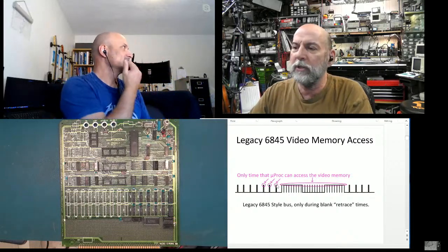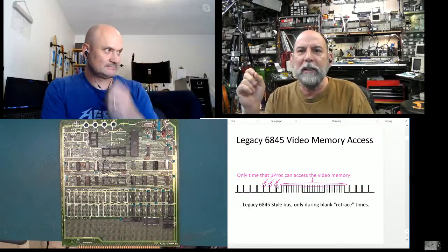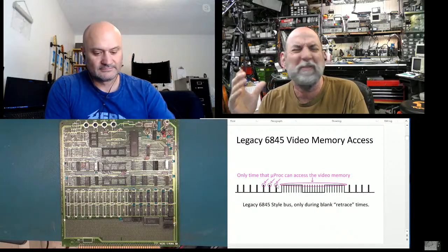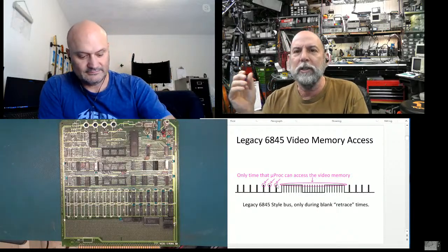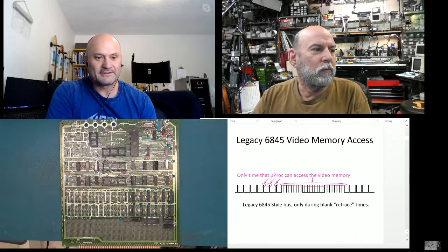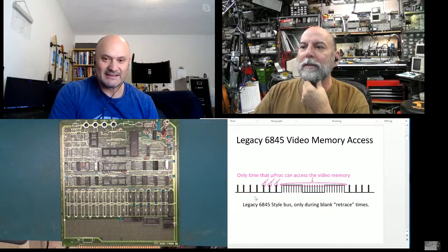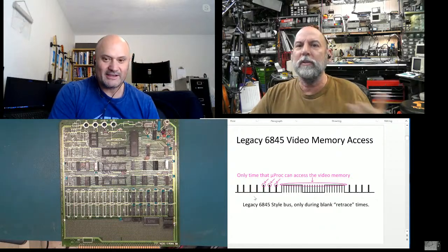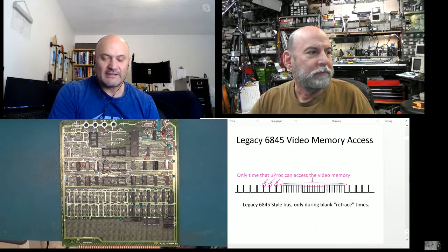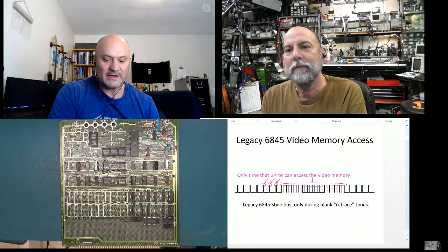I don't have something that shows the full frame, but it's real minimal. Out of 63 microseconds, you might get 6 or 7 microseconds, maybe 9, where you could write to the memory. It's eons of time by today's standards, but back then it was very limited. It's about one cycle per microsecond. And this was a fundamental limiting factor of 8-bit animation.